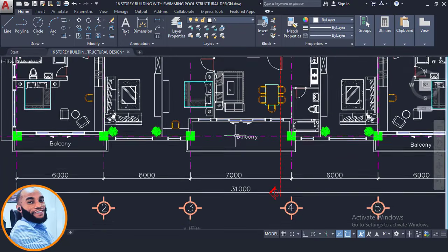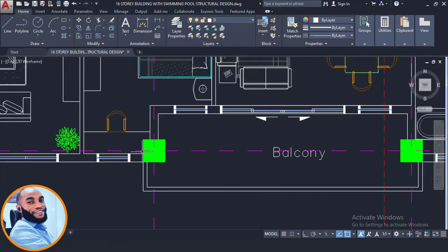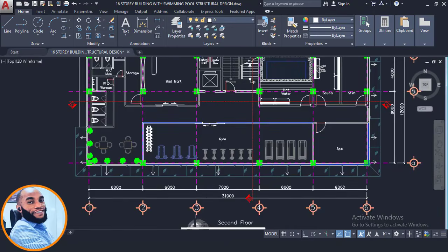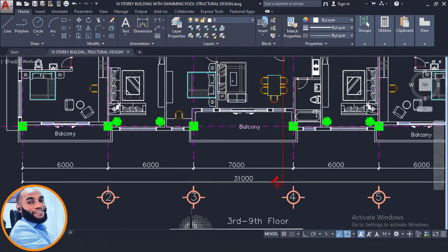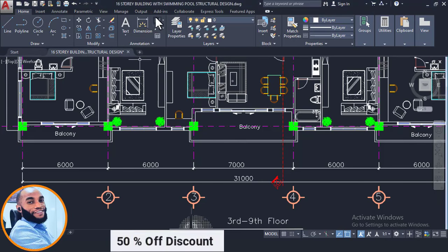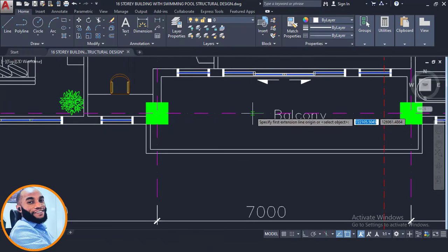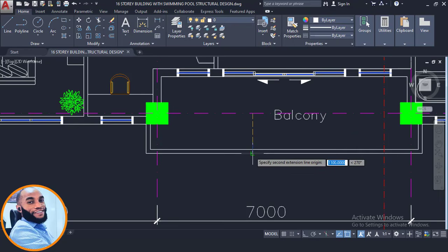And now this other one, knowing that we have a beam flowing all the way down, as you can see from what we have here before, we have a beam flowing all the way down here. So what happened now is that I will have to confirm again what is the length of that. Okay, so I'll do that by clicking on this first, and then dimension, and I'll come again, click again, confirm from the grid line all the way down to this place here.